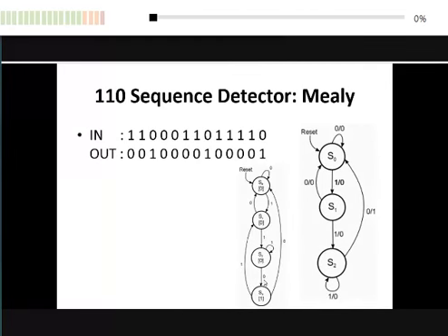But where are you going to restart? Is it S0 or S1, as we see in the Moore model? We always have to answer, where should we start? Is it S0 or S1 in this example? So if we know the next input is 0, it will restart at S0. We follow the Moore model. Why? Because at S0, there is an arc that stays at S0 if the next input is 0.